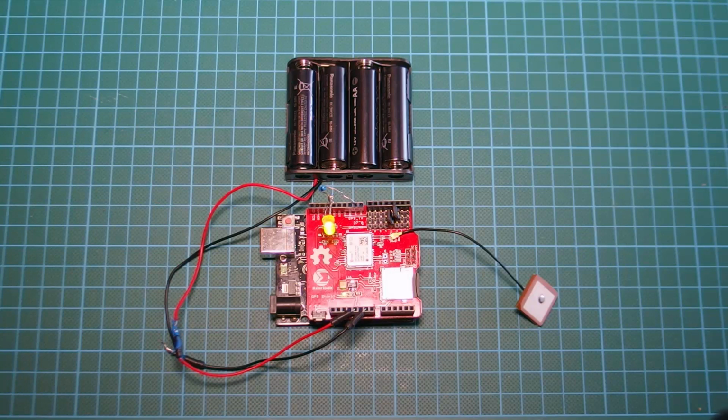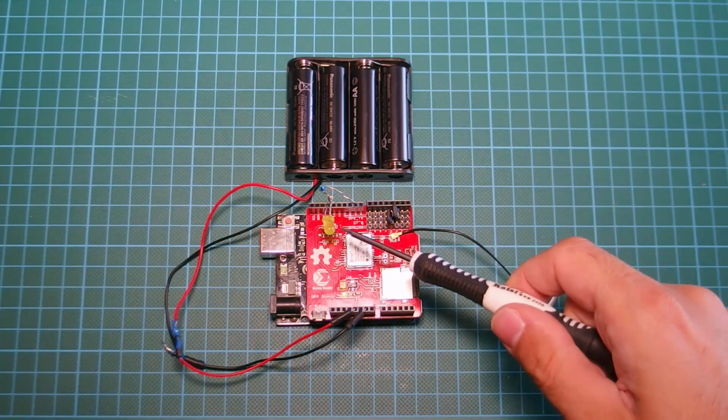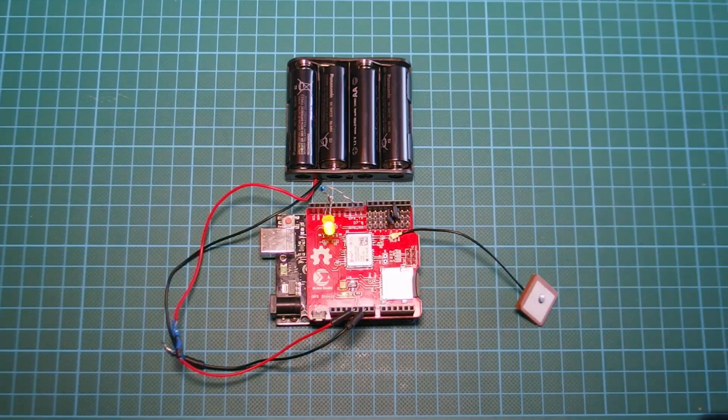If the LED is lit but not flashing, there was a problem with the SD card, so our project is not saving data. If the LED is flashing quickly, like it is right now, the SD card is working, but we don't have a position fix yet from GPS. If the LED is blinking once every 5 seconds, everything is working fine and data is stored to the SD card. Of course, indoors we can't have a GPS fix, so let's go outside.